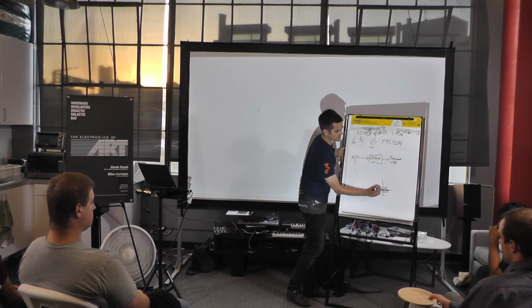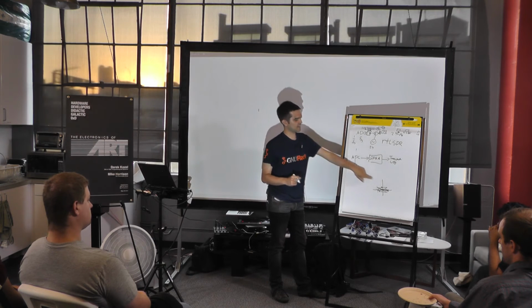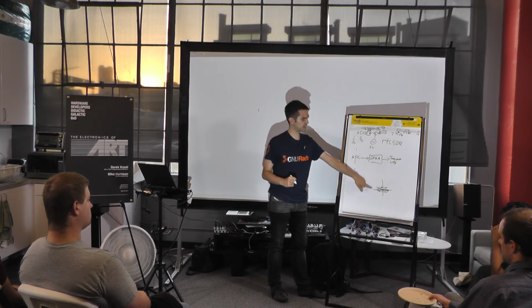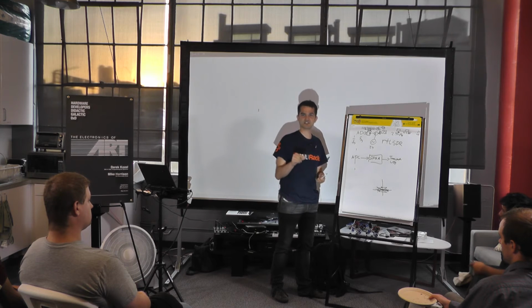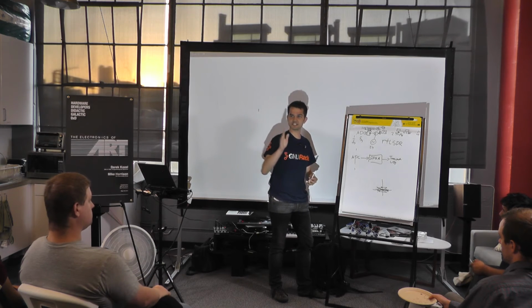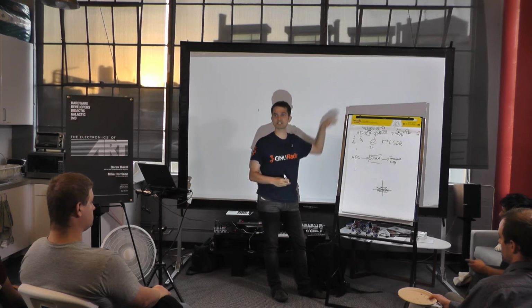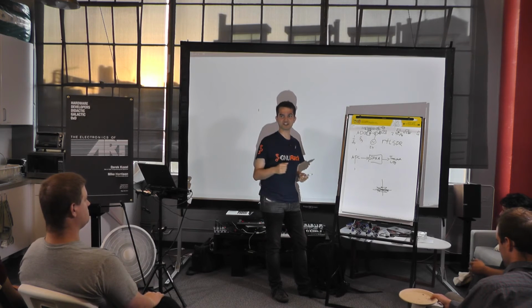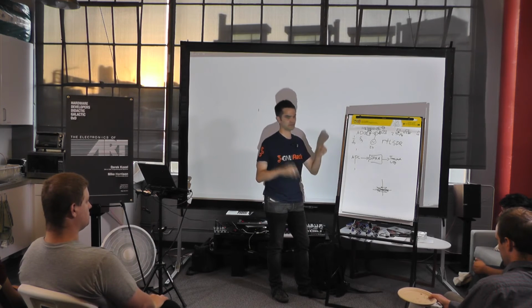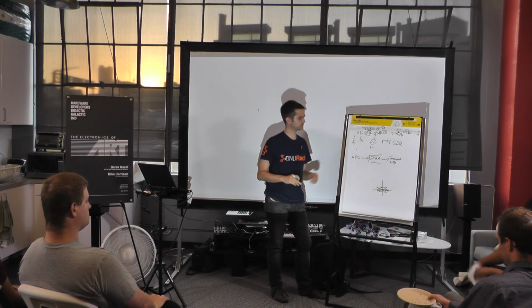So if you accidentally sample somewhere in the middle, because you're sampling really, really fast, and you think that that's a symbol, that's called inter-symbol interference, because you're seeing something that's not actually meant to be decoded. So you need to be sampling at exactly the right time. And so GNU Radio has time synchronization blocks that help you figure out when the transmitter sent a symbol and how frequently you should be sampling, and aligns you with that.